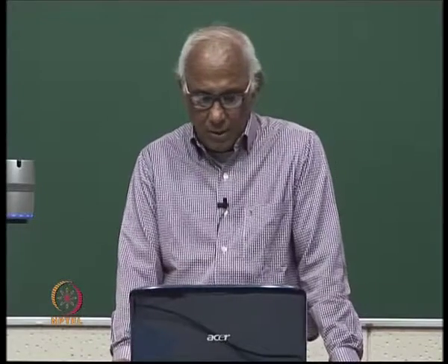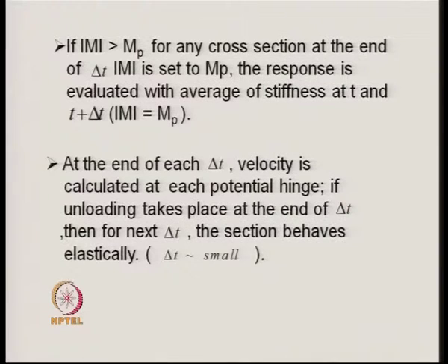Similarly, when we find that at the end of the time interval delta t an unloading is taking place, then also we do the same kind of calculation. We constantly monitor the velocities at the yield sections. These velocities could be the rotational velocity or the displacement velocity, depending upon the kind of problem we are solving.